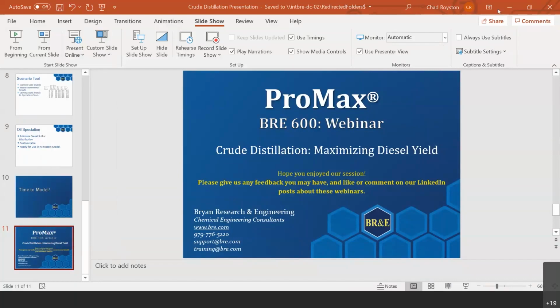Yeah, well, we have had good matching of plant data. We've primarily used this function for matching sulfur speciations for naphtha, cracked gas oil, and diesel cuts. I think it's designed to go a little bit heavier than that, but generally, you mentioned 397 components.